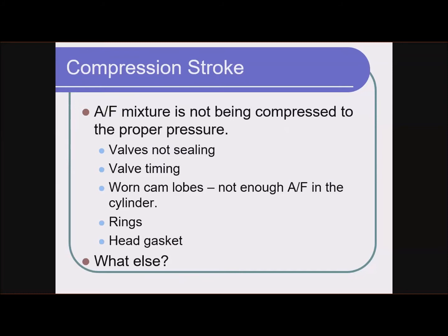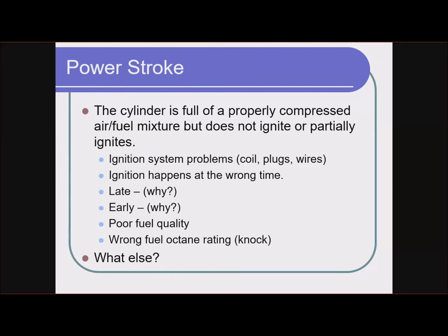And I've seen worse. We talked about pre-ignition earlier on, and in one slide you could see that if the pre-ignition went on long enough, it actually could burn a hole right through the top of the piston. And I've seen engines like that. I've seen pistons with holes right in the middle. And guess what you get for compression? Absolutely zero.